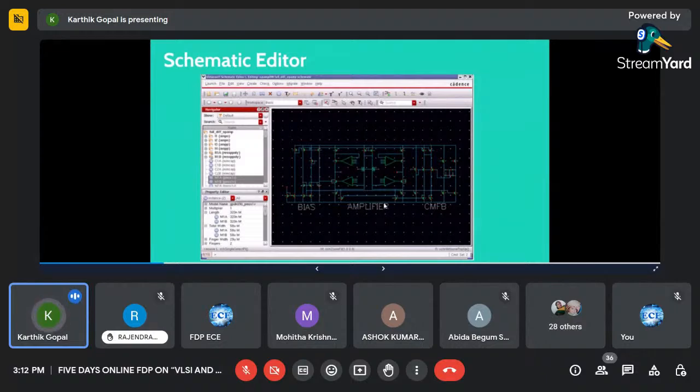So to simplify, let's say you have 200 transistors in a design. It is very difficult to place all the 200 in one single page. So what we do is we categorize them. So this op-amp symbol has some 10 or 20 transistors inside. So we symbolize it. So this makes the schematic readable and more intuitive to learn. So this is the schematic editor where we have all kinds of editing, wires, and we can place the MOSFET. So these MOSFETs are from the foundry. They will give you the model file. So this is how the schematic editor looks like.